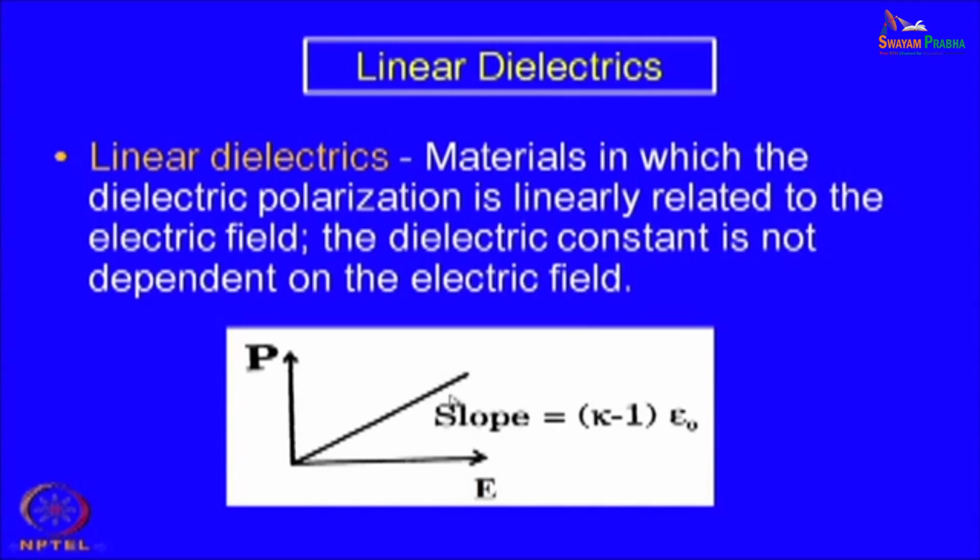except a group of mixed oxides which are known as ferroelectric materials, which will be discussed later in the class, maybe the next class. So, most of these materials are called linear dielectrics, except a group of materials which are called ferroelectric materials or piezoelectric materials. Those have non-linear characteristics. So, one can distinguish between the two groups of material depending on the characteristics of variation of dielectric constant as a function of applied field.